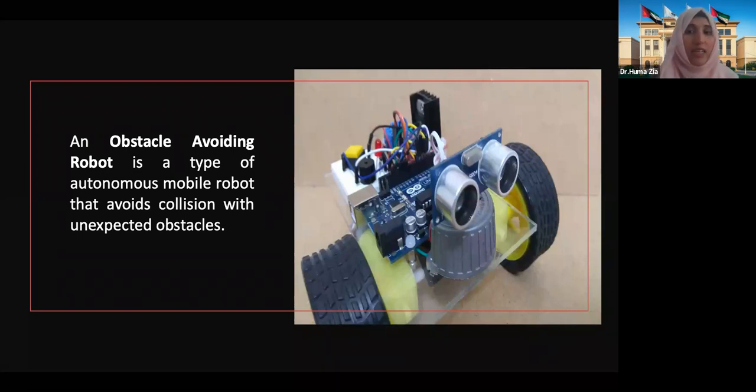Now, the robot design that we're going to be talking about will use 2 motors. The microcontroller will need 2 digital pins for direction control and 2 PWM pins for speed control. Speed is controlled for a motor using analog output, although Arduino doesn't have an analog output, so we actually use PWM pins for that.